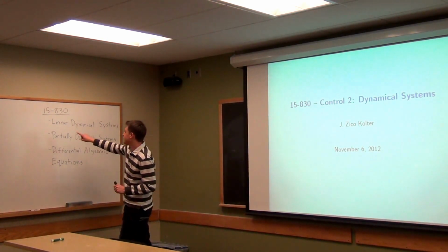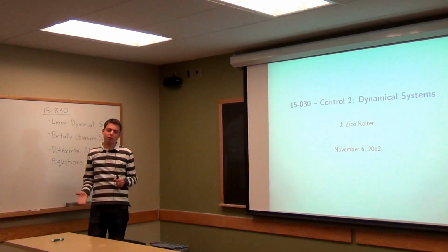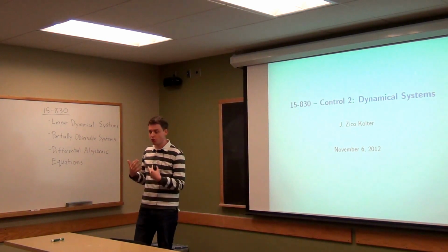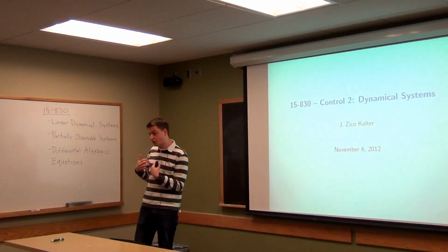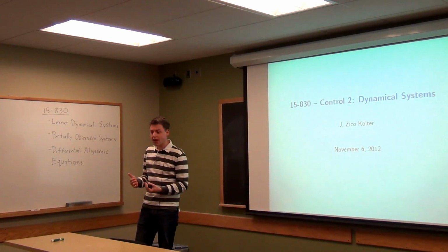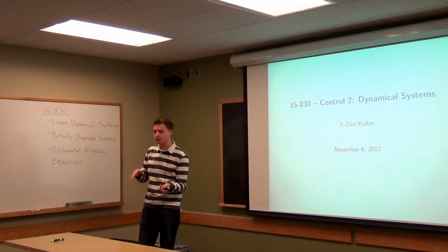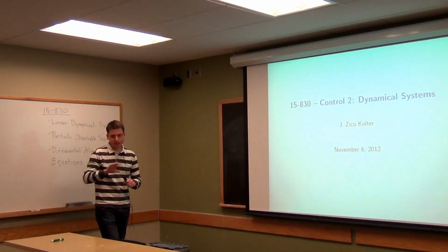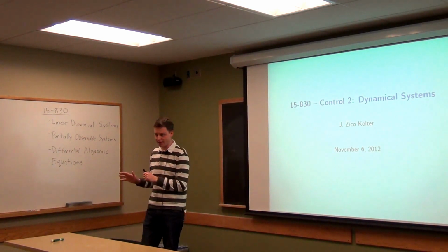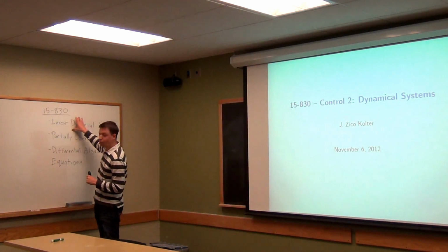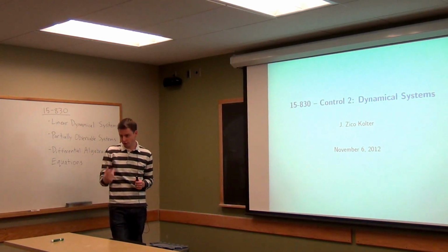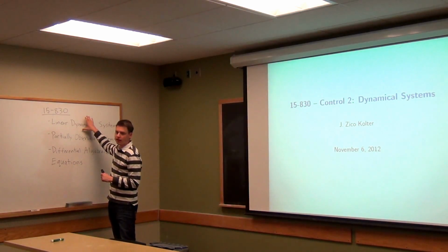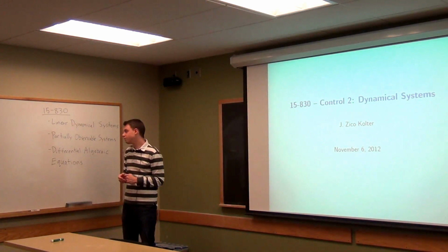So I'm going to talk some about linear dynamical systems. That's what we already saw last time, actually. I sort of motivated it saying that in an optimization task, you really want to have it be the case that our constraints are linear, so they can be convex, right? And to do that in our setting, we required, so far at least, that the dynamics are a linear function. So the next state evolves linearly from the past state. But the example I gave was pretty simple before, right? There was just one state variable, one control input. And so really you can get into much more detail, even in linear systems, about what dynamics are there.